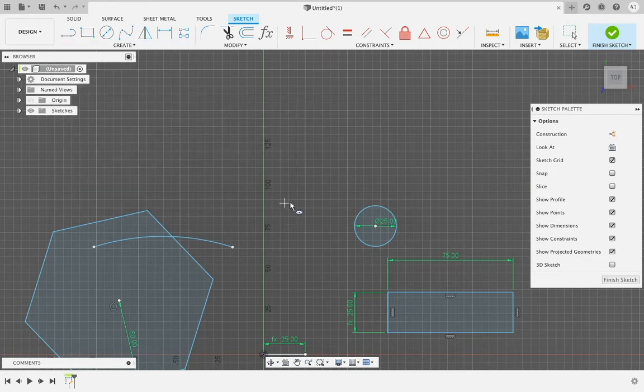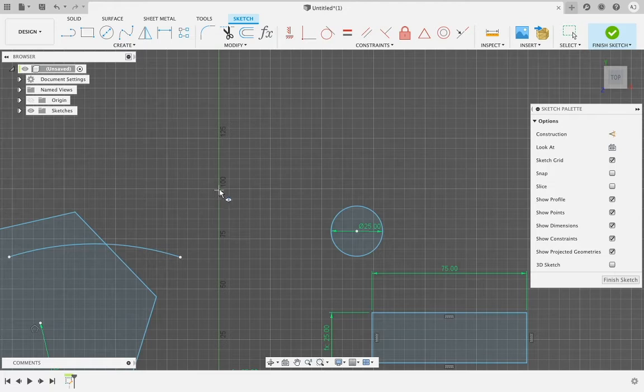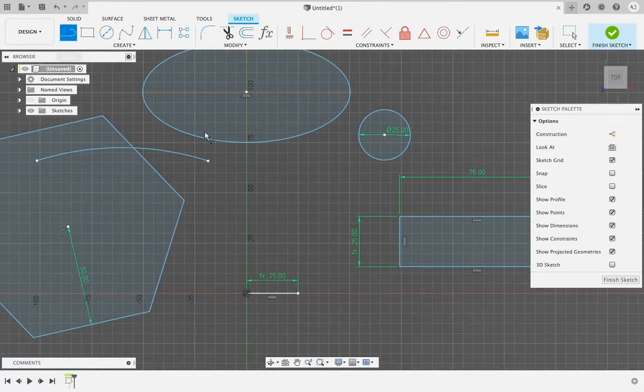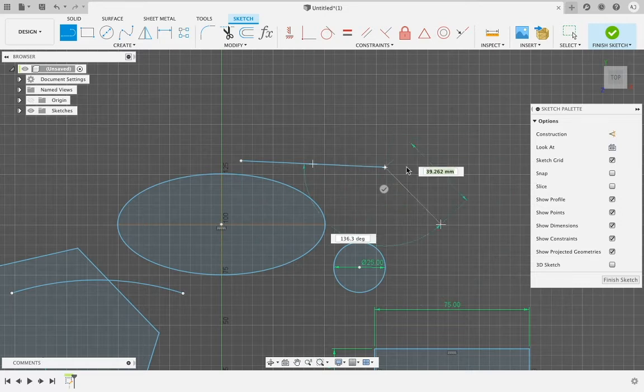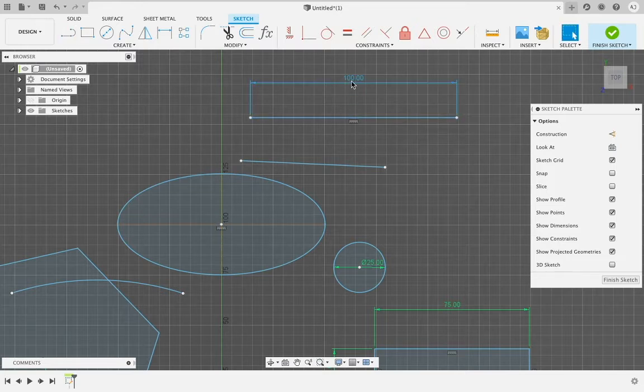Next is our ellipse tool. This is basically like a circle, but has some extra features to specify it differently. You can set its diameter, and then you can specify its width. Say if it's 100 by 50. You'll notice when you use a random measurement, say if I go like this, it will not come up with a piece on it. But to specify that is when you enter an actual measurement, and it stays like that. You can quickly select the dimension and delete it.